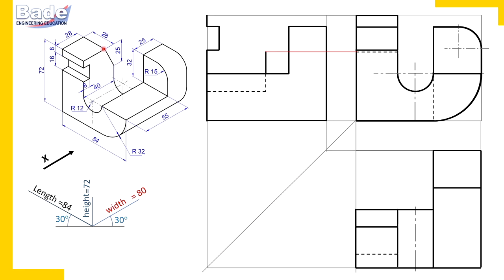You cannot draw a non-principal edge directly. You cannot draw non-principal edges directly unless you have the two ends of that edge. So this principal edge is 28 millimeters long here. And once you draw all the principal edges, you will be able to draw non-principal edges, that is, simply join these two corners. So this is how we have completed this surface.